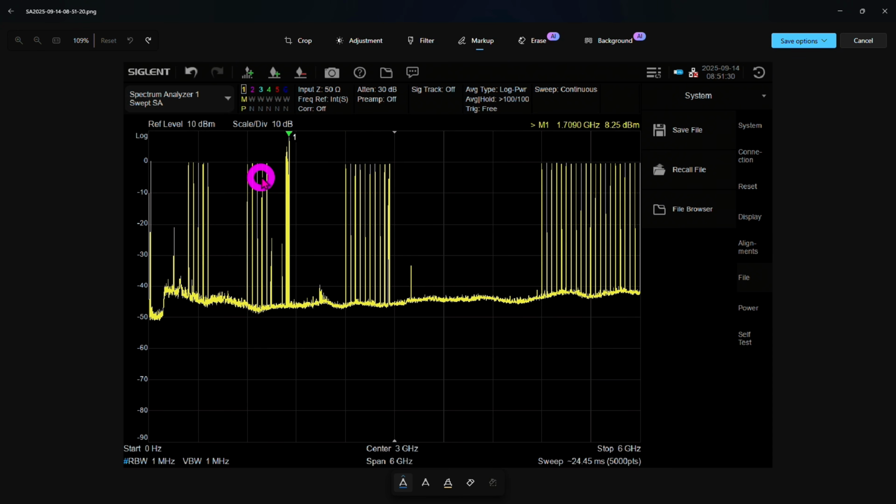And that's in fact exactly this section right over here. You can see that it doesn't work in its entire section because 1.5 gigahertz is right here. So in the upper range of the VCO frequency, it seems to be kind of working. But once it goes below about 1.2 gigahertz, the entire fractional-N gets unlocked. 1.2 gigahertz is right here. Every one of these divisions is 600 megahertz.